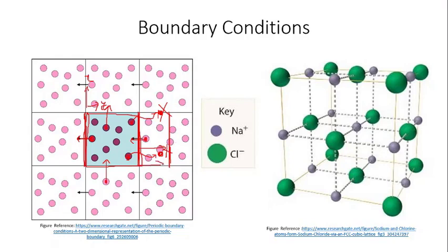So the boundary is extending up to the position where the atom moves. That is the shrink wrap boundary. Now the M, which means the boundary will be shrink wrapped but up to a minimum value. Suppose the minimum value is this much, and now the atom moved out of the minimum value, then the atom will be deleted. But if the atom moved inside the minimum value, then the atom will be considered. So these are all the boundary conditions.